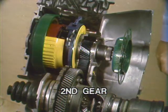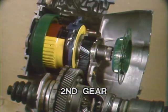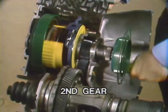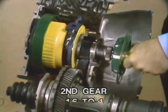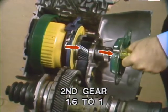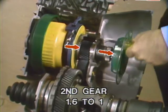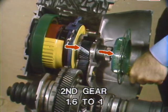Now on the hardware, Joe is tightening the band around the drum and has locked up the intermediate clutch. As he turns the intermediate shaft with the splitter planet carrier, the gear train output is in the same direction, but at a reduced speed. The second gear ratio is 1.6 to 1. Again, watch as Joe lines up the marks on the splitter carrier and the final drive input gear. Now the ratio. 1 turn of the input, 1.5 turns, just over 1.5 turns.